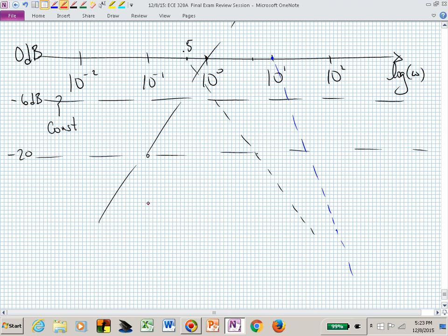So we are right here, and the 0 is always sloping, which means that we are always 6 dB below that slope due to the 0. And we just keep coming up until when? Until we reach the first new thing that's breaking, and that's going to be at 0.5. Once we get to 0.5, then the slope due to the pole at 0.5 cancels the slope of our 0 at the origin, and now we're flat.